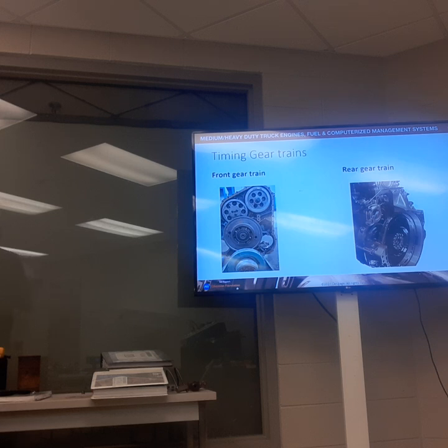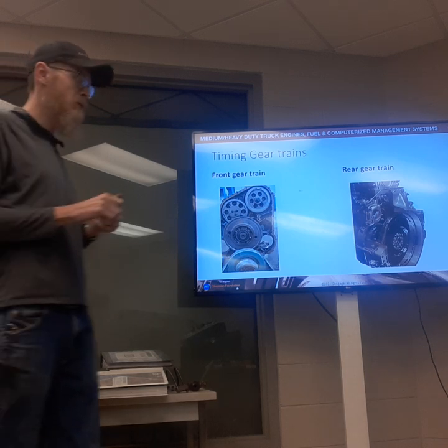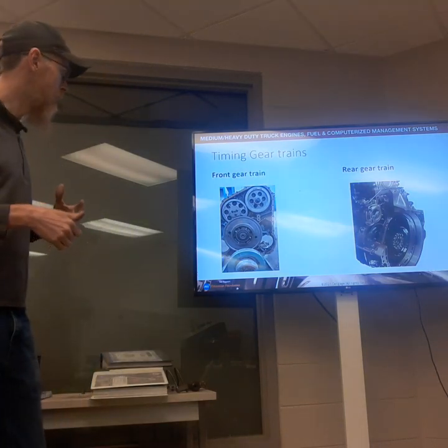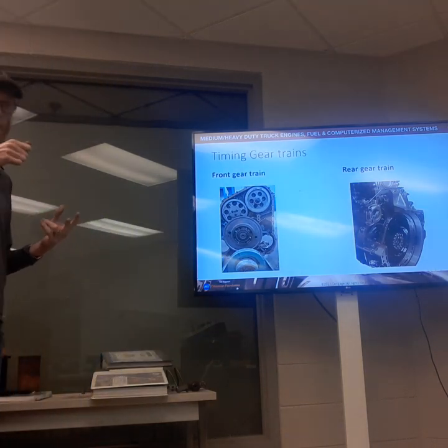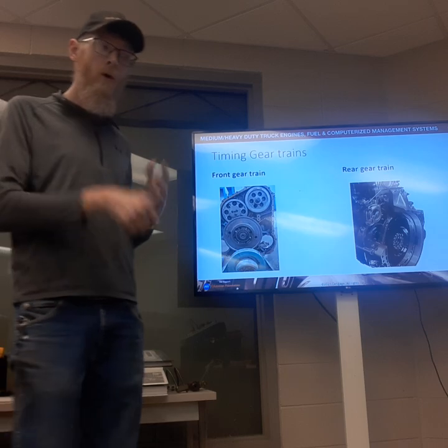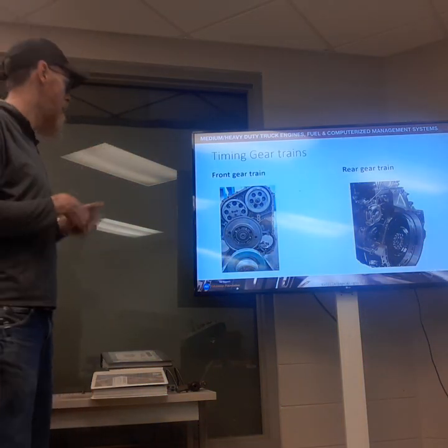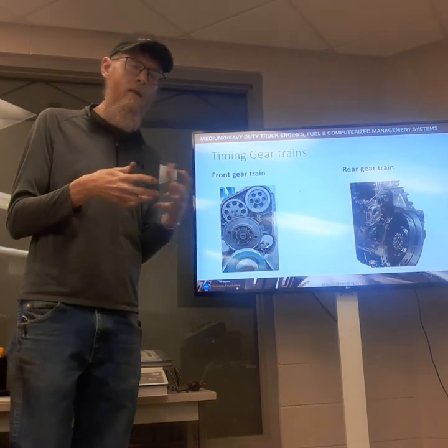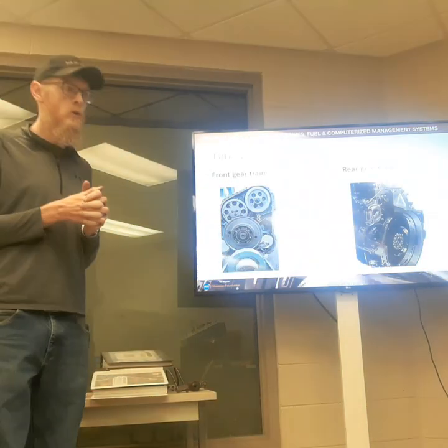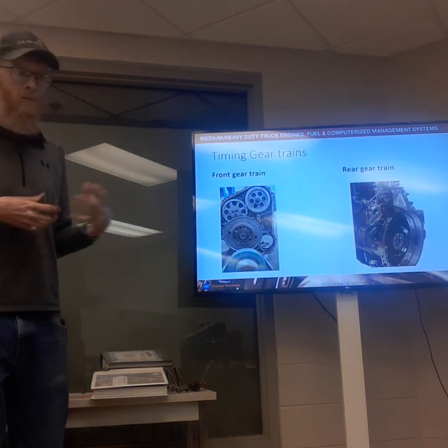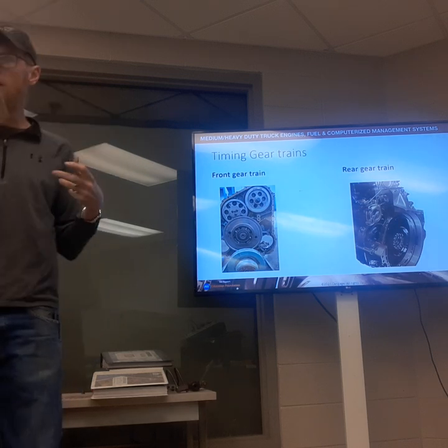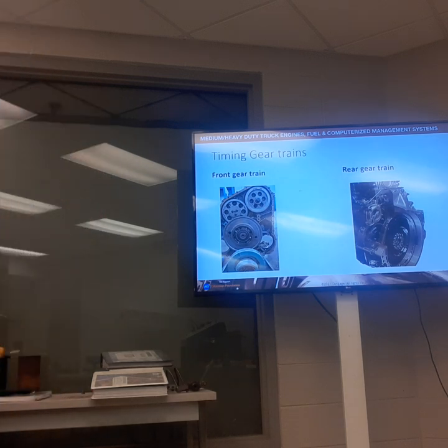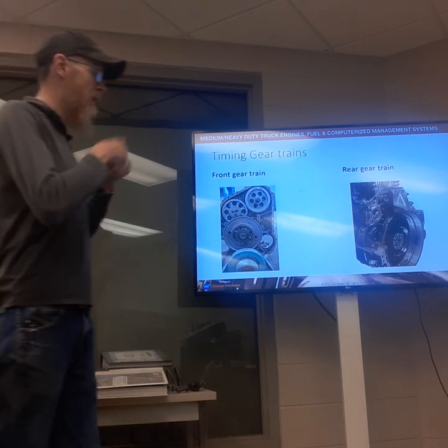So ultimately, we're using the crankshaft to drive our camshaft. In a lot of engines, we use it to drive a fuel pump, we use it to drive a water pump, etc. Air compressors, just about anything you can think of that uses mechanical rotation to do work, we could drive off the engine gear train. But our primary focus today is talking about our valve train.